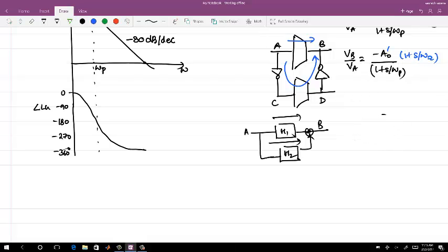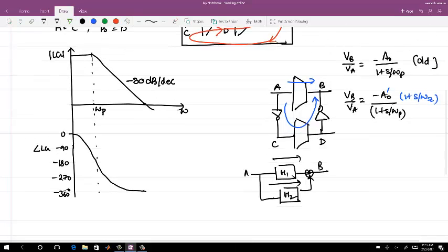The other thing is you can always work out all the equations, but I do not want to work out all the equations. I am giving you a simpler version. Effectively this inverter is adding a feed forward path, or an additional 0, which depends on where this 0 occurs. If I pick a 0 position here, and whether all the zeros will occur in the same position, you can work that out. This will actually change the phase.